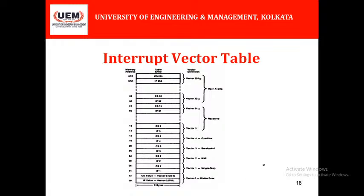So this is vector 0, which is the divide error type of interrupt. Vector 1 is single step. Vector 2 is NMI, the non-maskable interrupt. Vector 3 is the breakpoint interrupt, and vector 4 is the overflow interrupt. Vector 5 to vector 31 are reserved by the microprocessor for further operations. Vector 32 to vector 255 are available for the user, and we are observing the memory address of each vector.